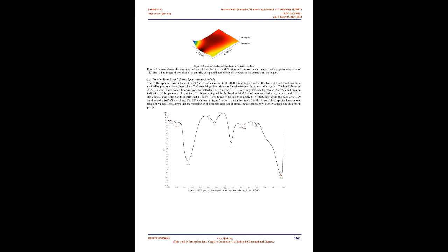2.2.3 Carbonization. In the course of the carbonization experiments, 15 grams of the activated samples were weighed into 4 different clean and pre-weighed crucibles, which were then introduced into the hot zone of a muffle furnace. The activated crushed peels were carbonized at a temperature of 300 degrees Celsius. The samples were held for 60 minutes in order to establish the optimum conditions for the process. The contents were then removed from the muffle furnace after the set period and cooled in open air for 1 hour. The produced activated carbon was then characterized using SEM and FTIR.